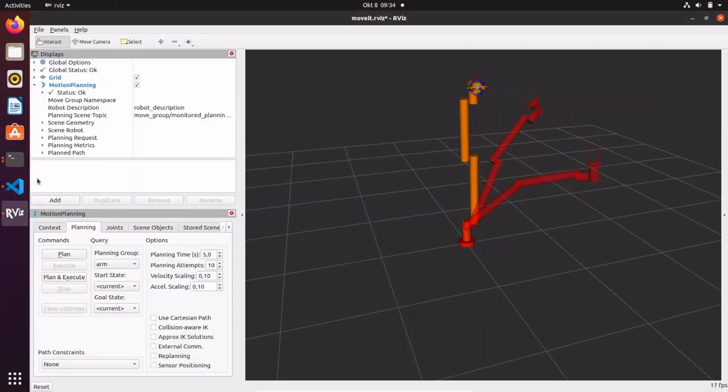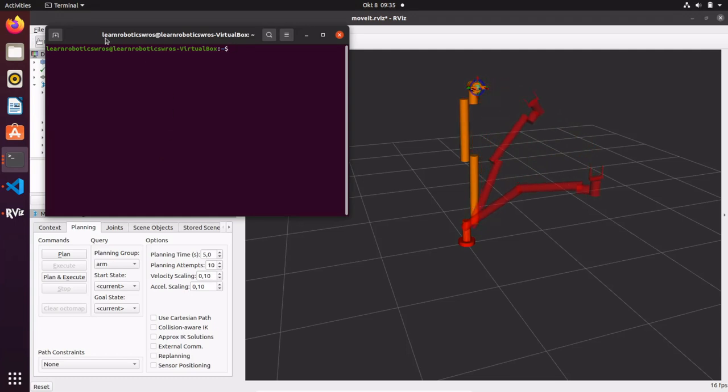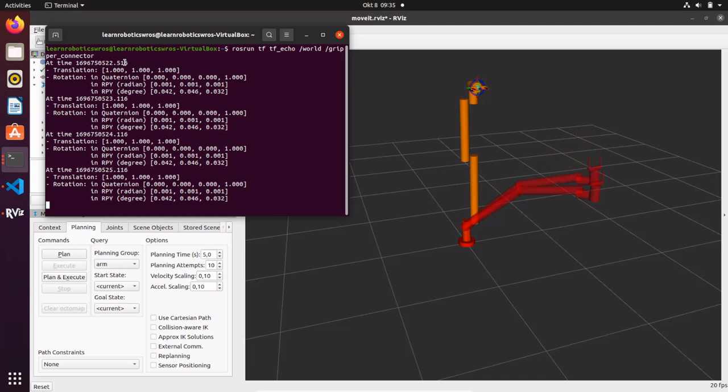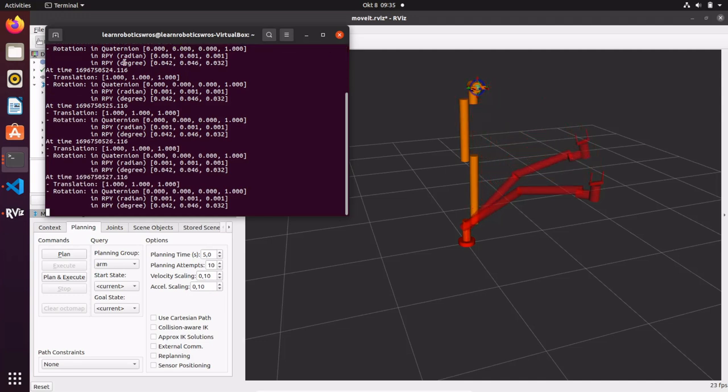Quaternions are a mathematical tool for identifying the orientation of a frame with respect of another. I know that it's difficult to imagine quaternions because you have 4 parameters, 1 real and 3 imaginary, and I guess that you are used to thinking of orientation with respect of roll, pitch and yaw, like what you are doing by moving the end effector in Rviz by using the MoveIt plugin.